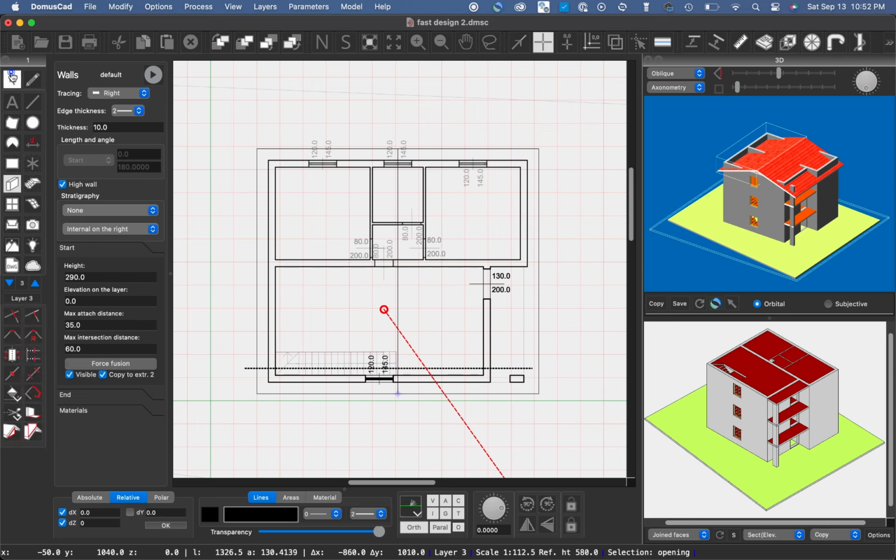I use the scissors tool in the palette at the bottom left and choose the active element option. I click on the walls icon to put the walls as active elements. I trace the scissors along the center line of the roof, so as to divide the underlying walls below your part of the roof.